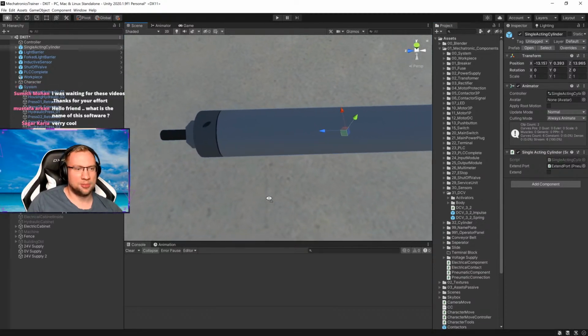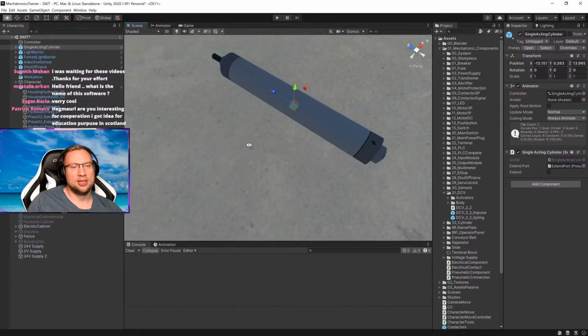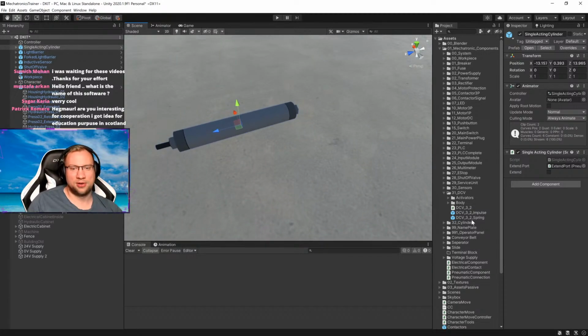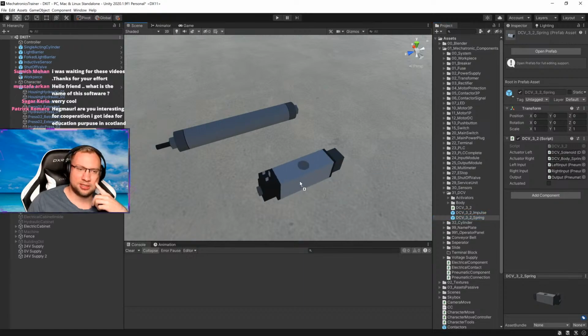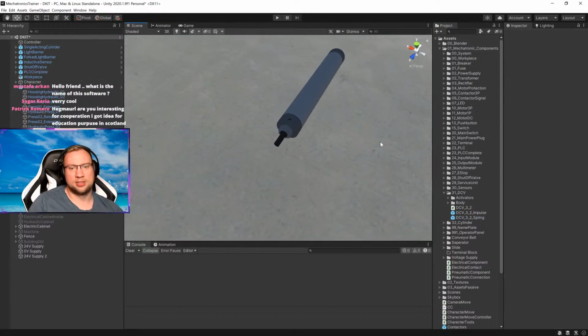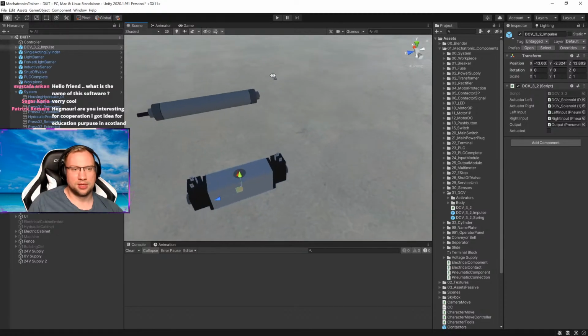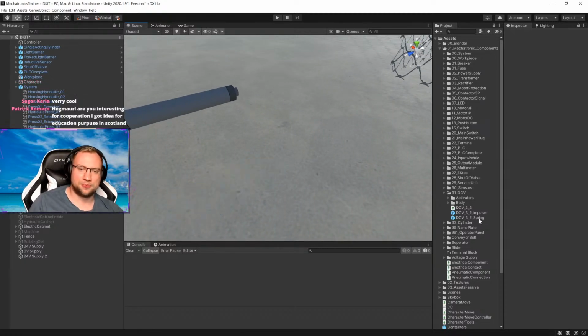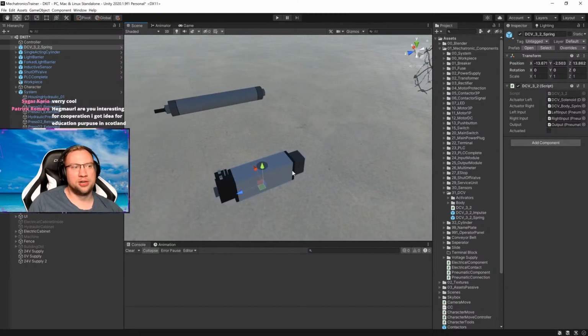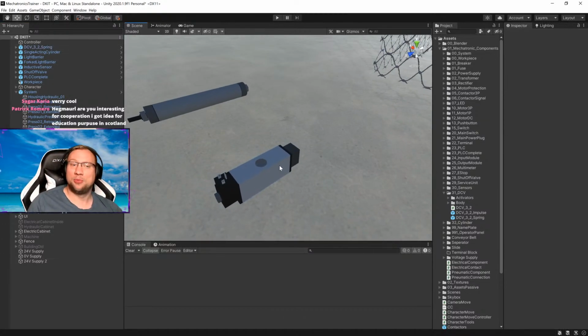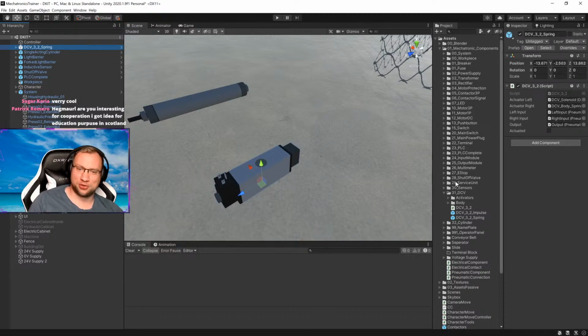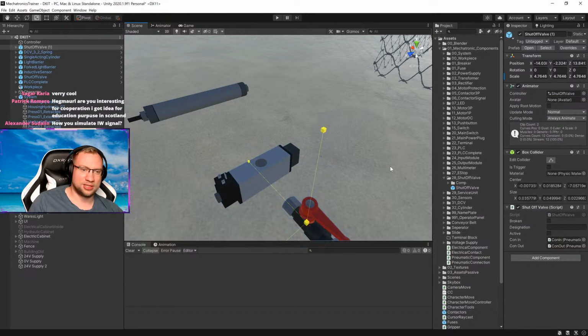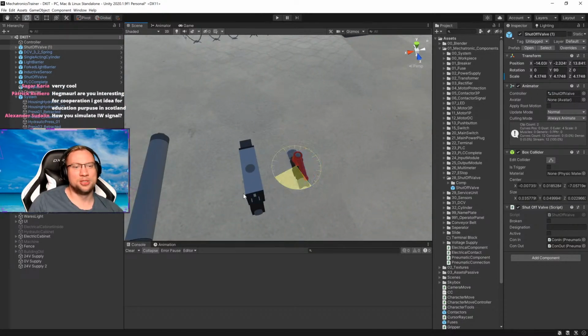It's got two ports up here, an outlet and an inlet, and we need to connect pressured air, right? So I've got different DCVs, like a spring return. Let's take the spring return actually. I've got the spring return DCV that I can connect to different voltages, so it's really voltage sensitive. But where does the pressured air come from? Of course, the DCV needs to be connected to a pressure source, and I've got this as a pressure source right now, which is not a pressure source, but it kind of is. Usually you have a compressor before.